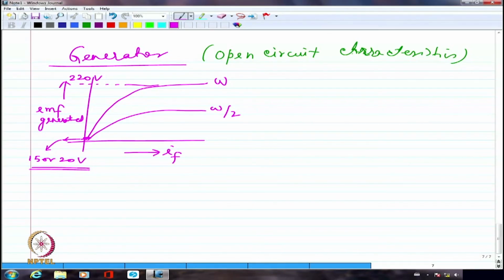If I apply a constant field current, I should have a constant voltage being generated. I am putting in a variable field current because I want to know the capability of my DC machine, that is, what kind of back EMF constant it has. I can get that from this, because I know the speed at which I am rotating the machine and the field current I am applying.